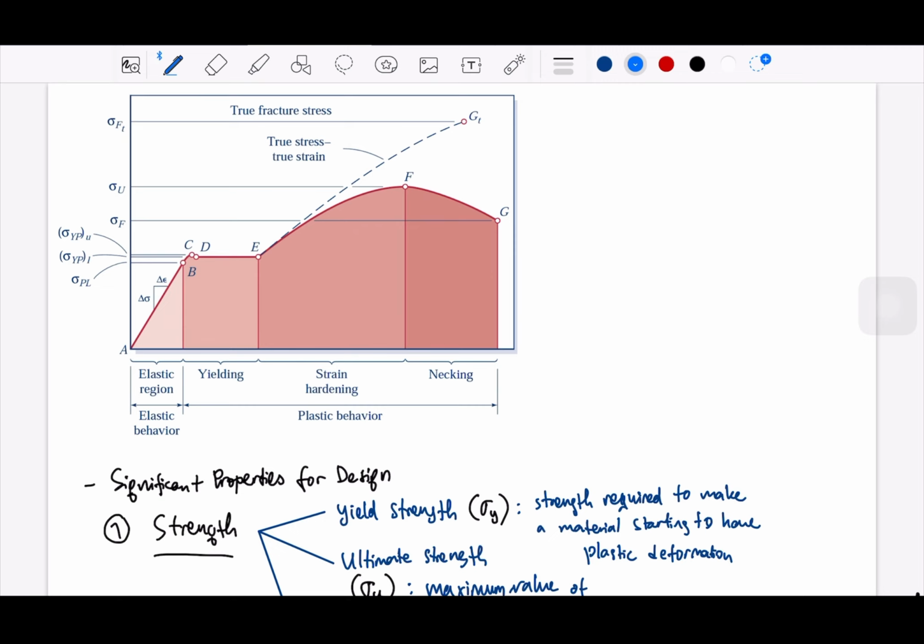And even aside from this stress strain curve, for the basic part in material science, you should know one or two phase diagrams, and a typical phase diagram for material science is the carbon steel, right? The austenitic steel, the ferrite, the alpha ferrite, and you need to know exactly the temperatures, at least for the large portions. Okay, so that's the thing. As a material scientist, that's what you need to pay attention to, because that's really basic.